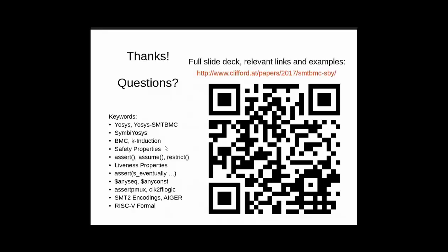Hi, Ian Singleton, Synopsys. Am I right in thinking from your slides that if you were to use this along with the Verific front-end parser, then it would support the full SVLRM and you would be able to write temporal properties in SVA? That's the goal. Okay. The thing is, Verific, as soon as it comes to SVA properties and stuff like that, the netlisted output is not actually a netlist you can execute as it is. This is more like a netlist version of a parse tree. Yep.